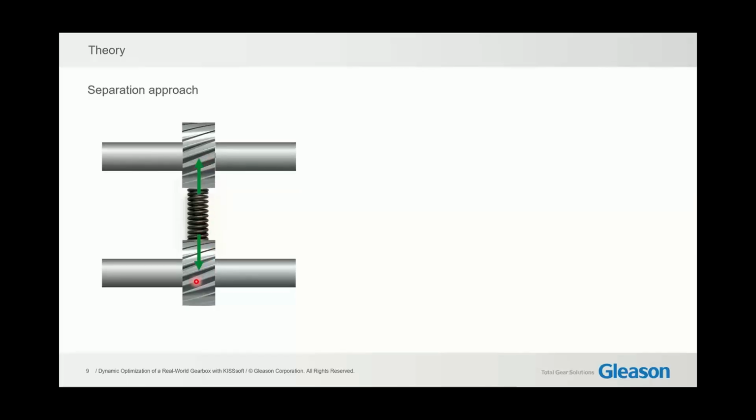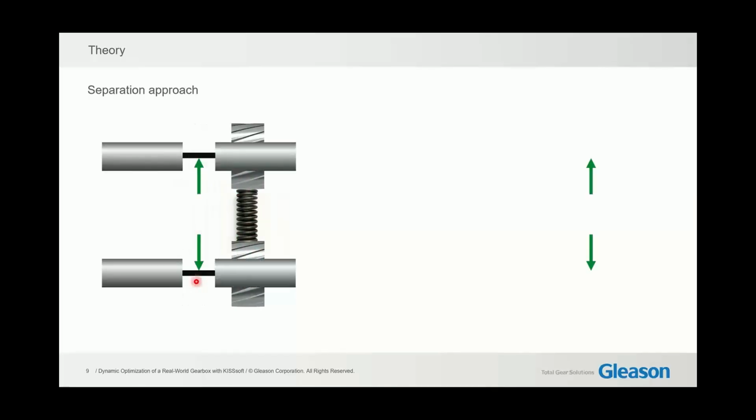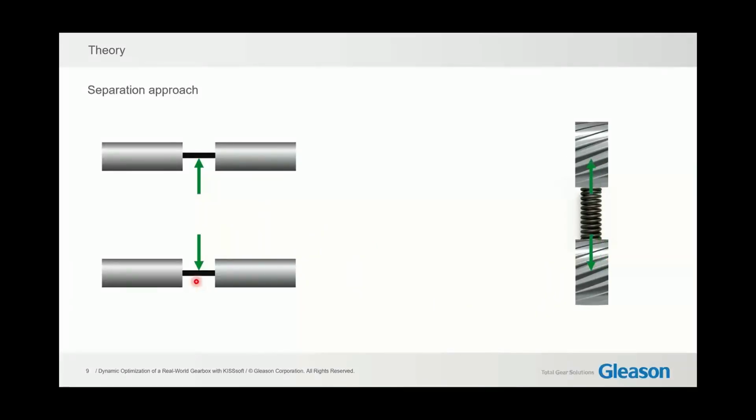This is our gear meshing force. We took the gears out. So we have now an ordinary differential equation left for the shaft and the second one for the gear stage. And the common mutual component in both is this gear meshing force Fz of t that can be represented with some Fourier sum.